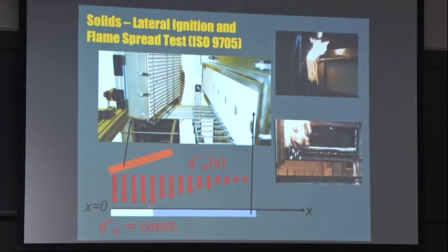And then the flame spread will start spreading into less and less external heat flux. Now the question is, why does he do this decay? And this is the most intelligent part of the whole test. So here you have a decay, and he achieves this decay by putting an angle between the radiant panel and the sample.